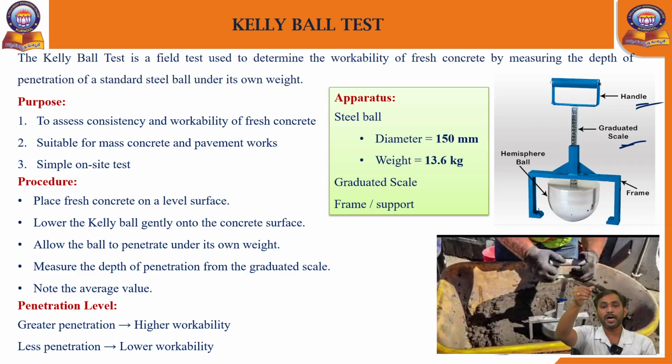The ball will penetrate under its own weight. When the penetration stops, measure the depth from the graduated scale.